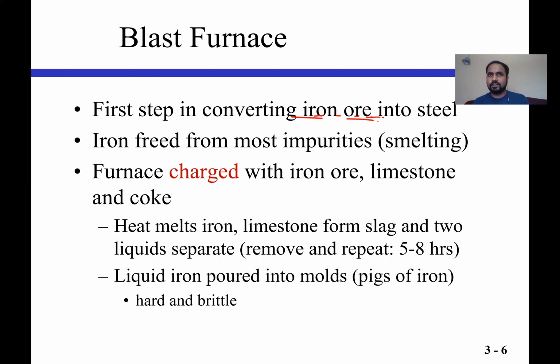And we take this iron ore, we mix it with limestone and something called coke. This coke is not the Coca-Cola. This is basically coke you get after heating coal in the absence of air. In the anaerobic condition, if you heat coal, it transforms into a black